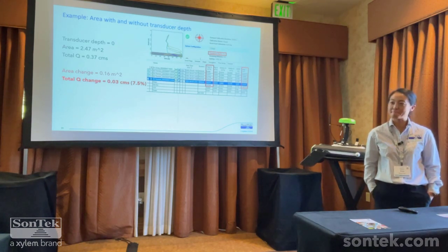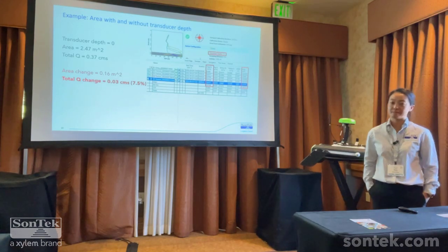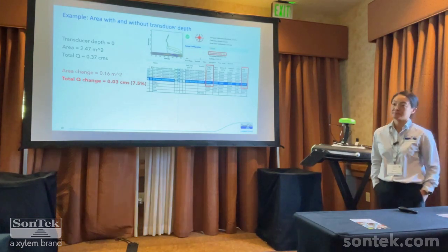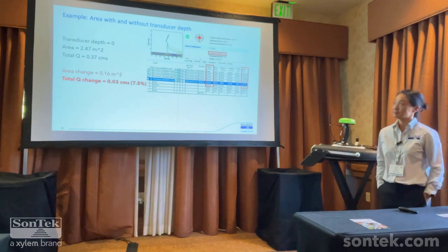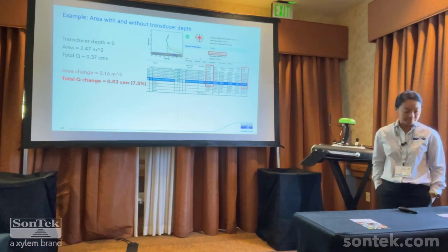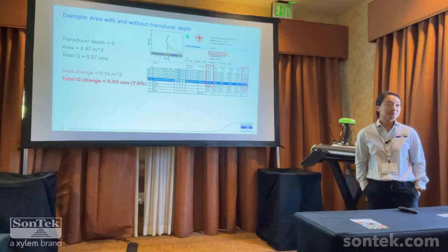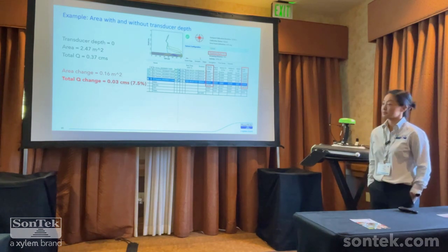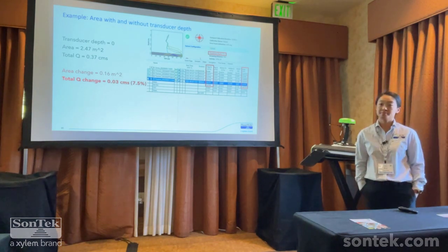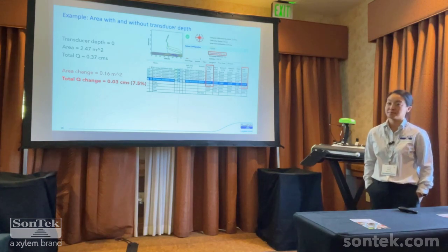Air is the enemy of the acoustics. If there's a lot of air getting entrained, like Xue showed in that SNR plot up there, you'll see the beams spike way higher in the water column. That's because the acoustic frequencies we use don't propagate through air, and if it's anything more than tiny air bubbles, it blocks the signal and it doesn't work.